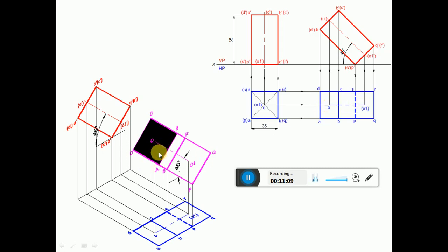This is also quite evident from here. When you look from the top surface, ABCD is near to the observer, it is visible, and then you have a rectangular face which is BQRC. That is, BQRC is visible. So that means it becomes an opaque surface, and this also becomes an opaque surface. Naturally PS is beneath that, so PS becomes invisible.